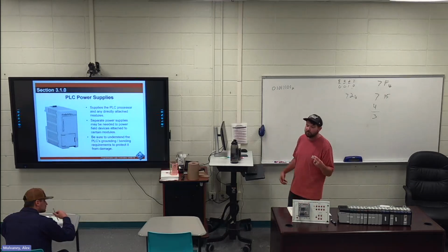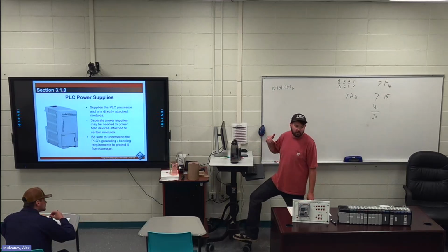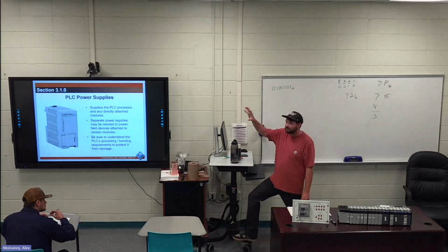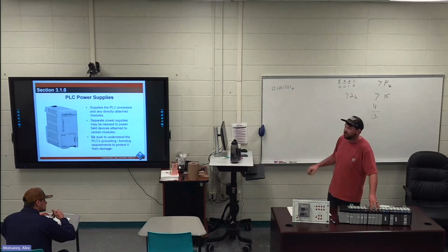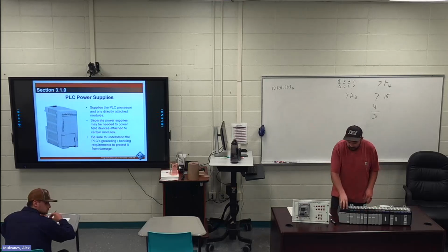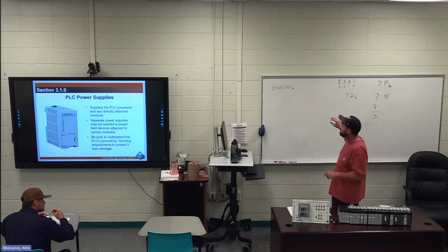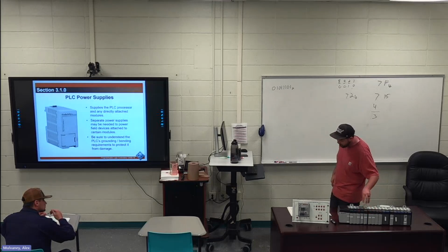You should have gone through a lot of electrical classes. Most of our stuff is in series circuits, and stuff is paralleled off of that, like the lights. With a PLC, older PLCs used to have to run to contactors to control more things. Now these power supplies will power the lights and pieces of instrumentation. Instrumentation has gotten better. It doesn't take as many volts to get a differential pressure meter to come on, so it's not as much of a load on this.